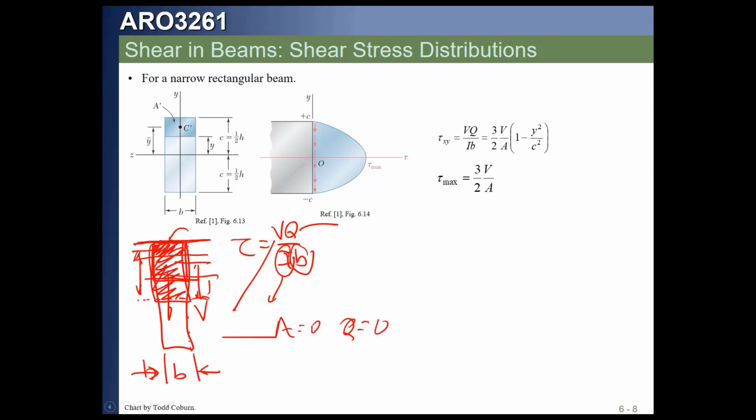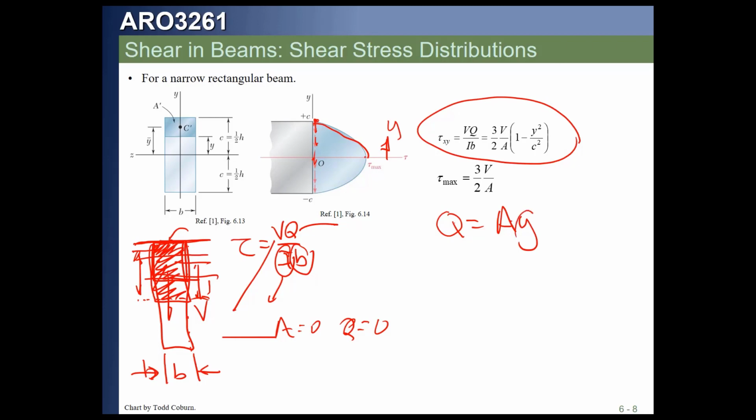That's what this shows. We see that this equation written out with calculus is going to give you a change in shear flow. Now it looks like all the little arrows are going down like this, but what happens is the magnitude is going from 0 at the top to some maximum value. Now our Q, remember, is A times Y, right? Our Y is from the centroidal axis moving upward. That's our Y dimension. Our Y is the dimension from here to the centroid of the piece.